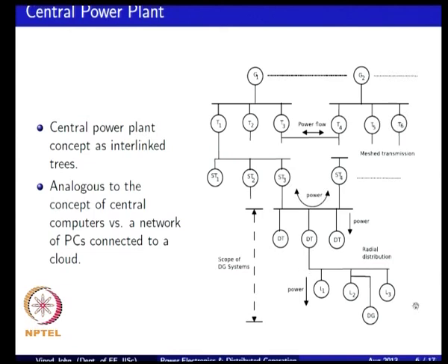Traditionally you did not have distributed generators connected to the distribution feeders, and the power flow from the distribution transformer onwards was unidirectional. But now when you have a DG source connected, you are looking at the potential for bidirectional power flow even on your radial distribution systems, and this has implications.